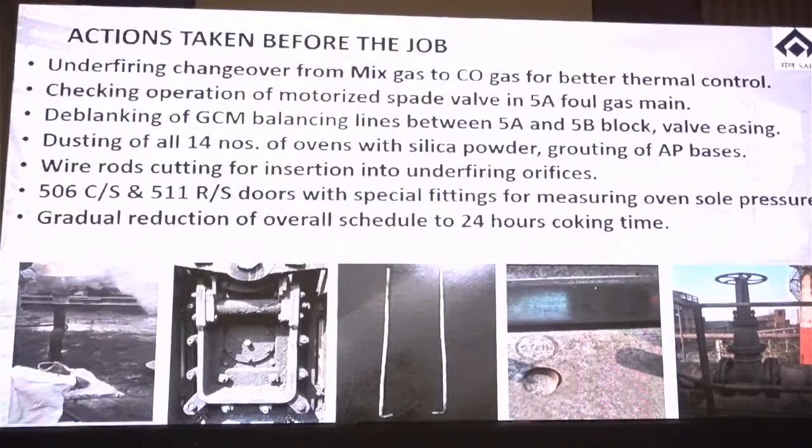Under firing changeover, we had to change it over anyway to coke oven gas from mixed gas. Normally this battery runs in mixed gas, but we did it to coke oven gas, as well as all the batteries, because the blast furnaces were going down. All the motorized split valves that are not operated regularly, we checked beforehand, as we didn't want problems when we had to operate them.